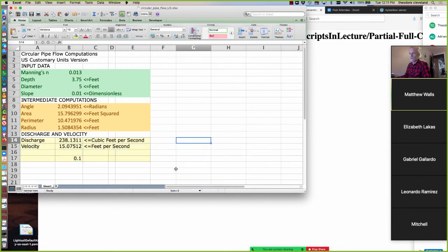Let's go yellow. So you can give yourself visual reminders. Let's go with a 6-foot diameter pipe, and we'll go 5 feet deep in it. And if we do that, a 6-foot pipe with 5 feet will carry 430 CFS at 17 feet per second, which is a bit much.